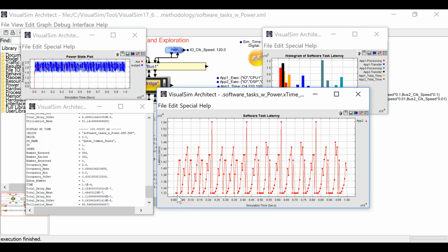I noticed here my latency did not start at 1 microsecond, but started at 1.32 microseconds. But earlier on, we were at 1.55. Now we're at 1.54. So the 200 megahertz actually narrows down the range of latency as opposed to the 400 megahertz, where it's much wider.